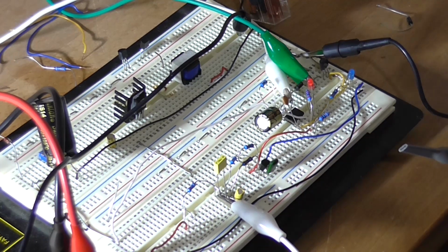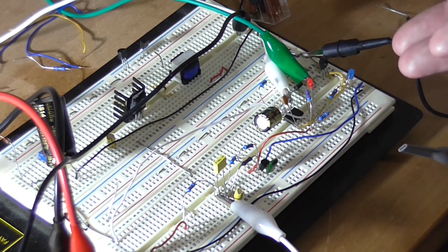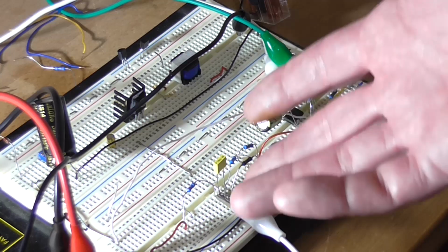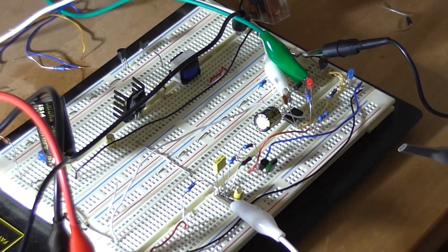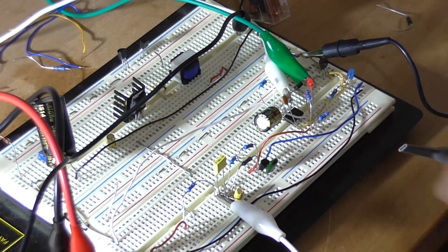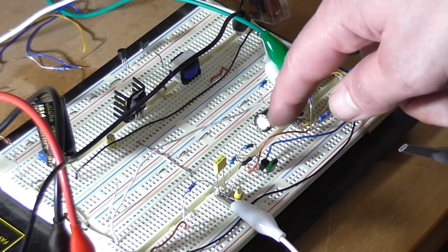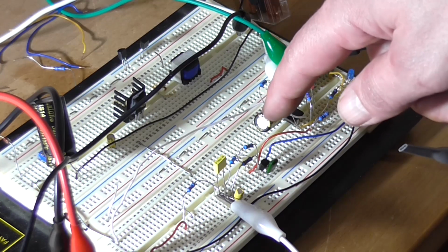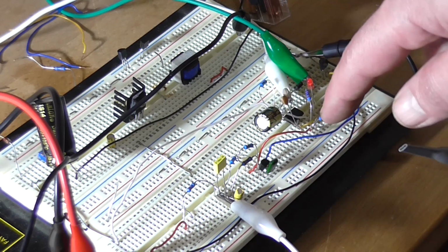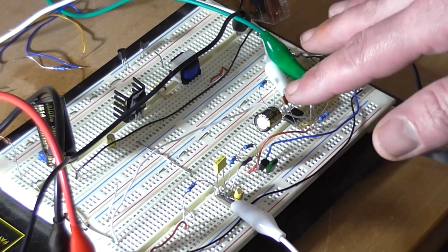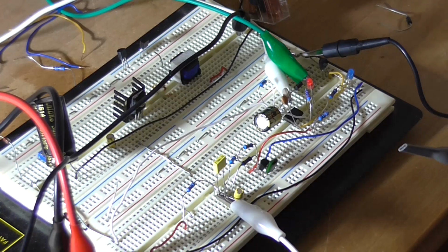But all this was basically an experiment with the 555 and making a sound detection switch, which, yeah, it's not the best. There are other options you could do. You could use an op amp here at the input instead and give it much more gain and just reconfigure the 555 timer to work happily with it.